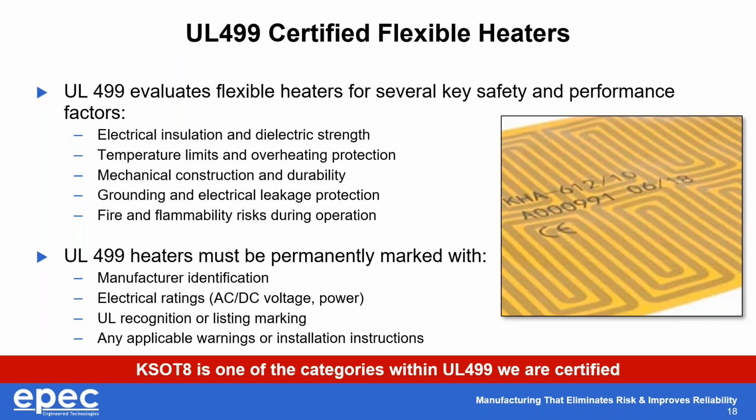Another major component of the UL 499 testing is to make sure that the device is properly grounded and any potential electrical leakage is mitigated through various design measures. Lastly, and most importantly, the materials that the heater is built with must self-extinguish when exposed to a flame.